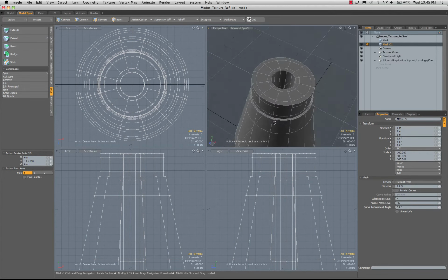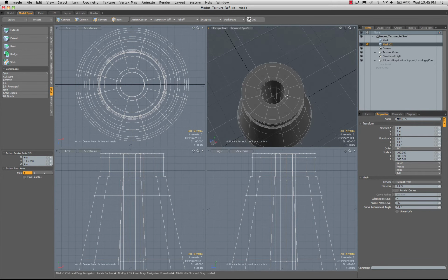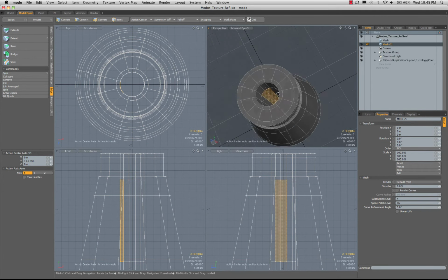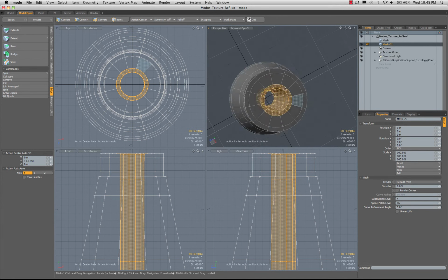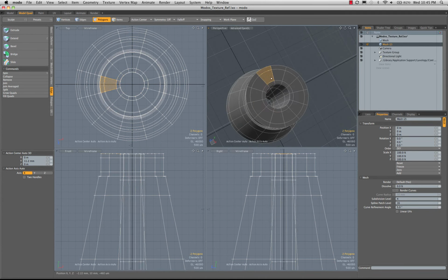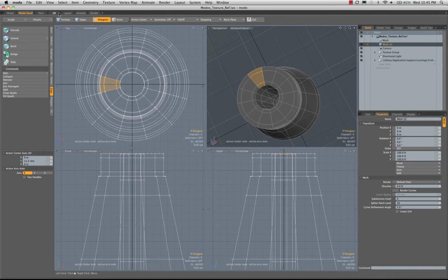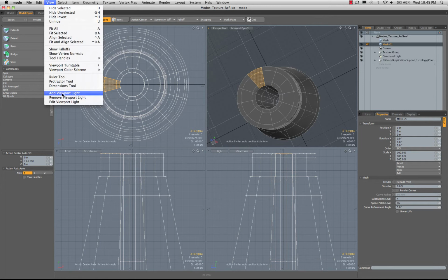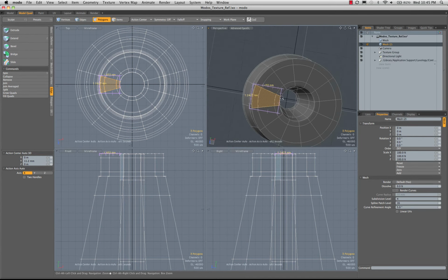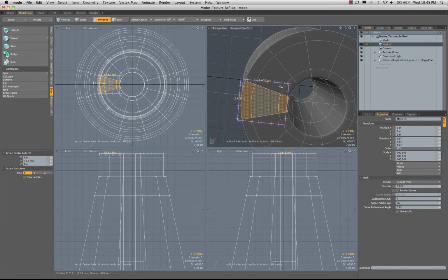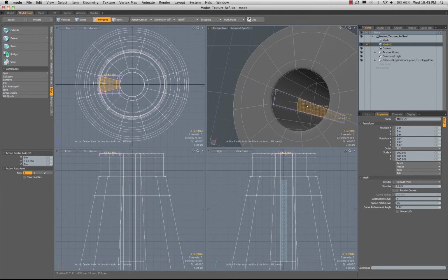And now looking at this, I think I may have gotten the wrong measurement, so it's good to double check. That's why I really recommend actually having the actual toy set there with you to look at. And I think here I can get a measurement on this. Let's go to our view and our dimensions tool. We'll turn that on, and you can see this is coming in at 1.4 millimeters. I think this is only supposed to be 0.8 if I measured it correctly.